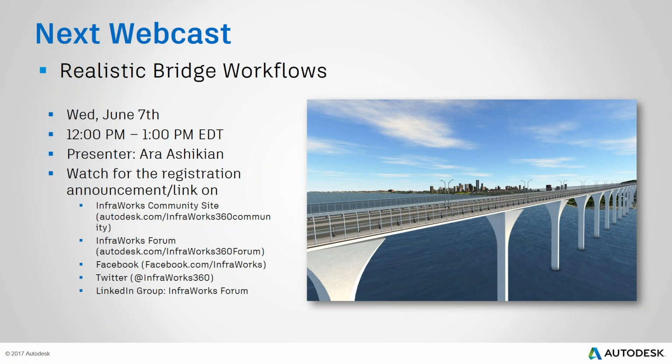Okay, so first of all, the geotechnical module, when you're creating surfaces, when you're looking at alignments, etc., will work with data shortcuts. So when you're generating a geotechnical profile view, you can click on a shortcut. When you're referencing a Civil 3D surface as an existing ground surface, they can all come through data shortcuts.